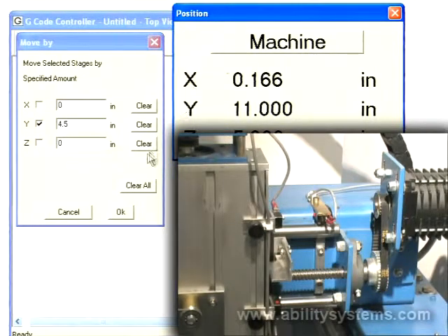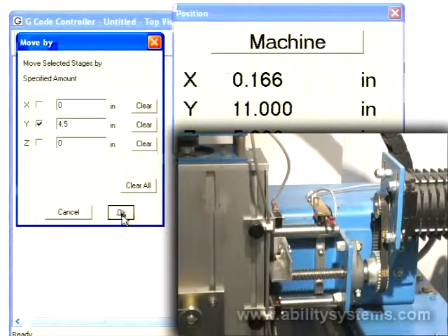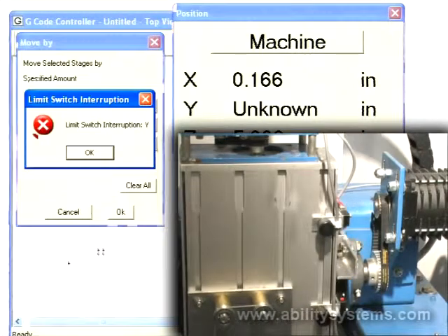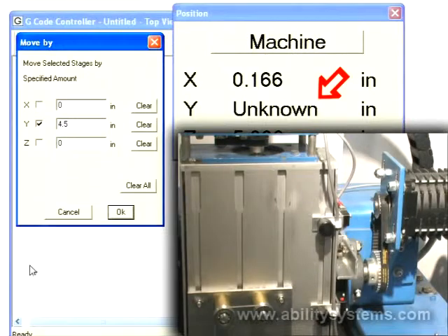Uncontrolled stopping occurs when an end limit switch abruptly interrupts any movement that requires acceleration. If acceleration is required, position information is not considered reliable if the motion is abruptly terminated. In such cases, Indexer LPT abandons position tracking on all affected motors until the home position is re-established.